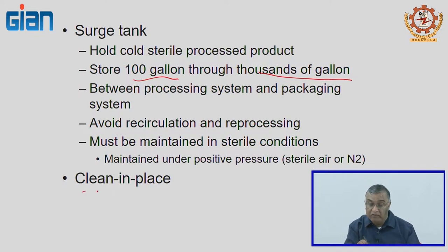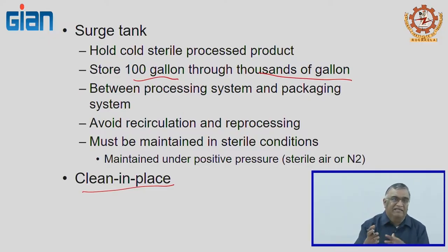And then you are going to fill this into a consumer package in an aseptic filling approach. We will talk about cleaning and sanitation later on, but basically your processed product is packaged inside a pouch, and you want the environment where that filling happens to be free from any bacteria.